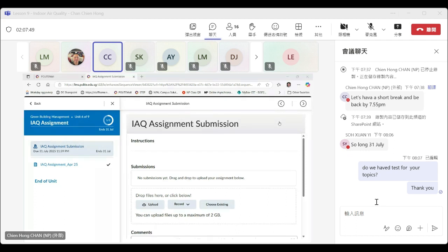So when you make the observations, you can also comment on whether the air conditioning system diffusers are adequate, and whether the return air path is near to where the heat is, so that they can effectively remove the hotter air, or the polluted air. Those are the additional comments that you can make, right?